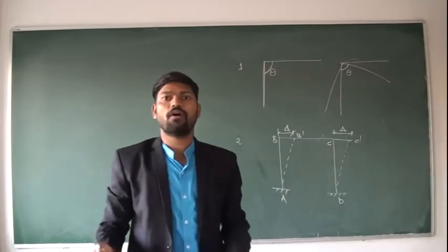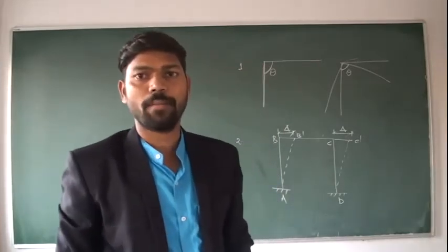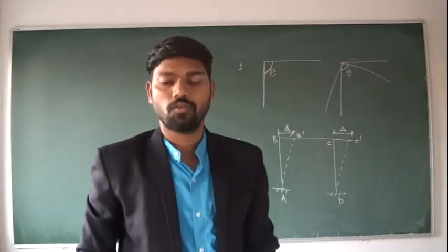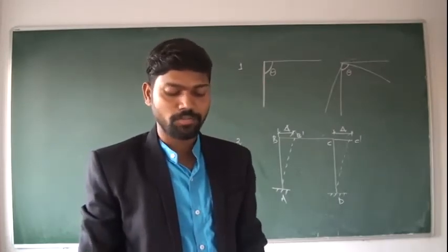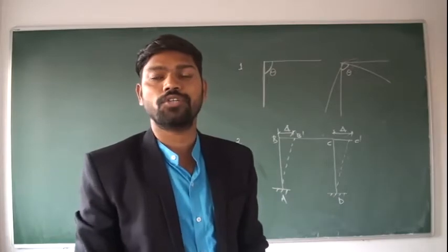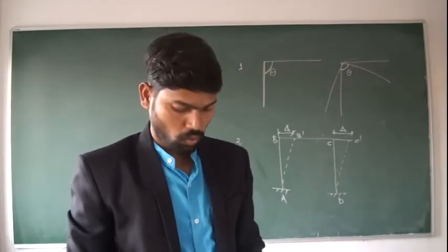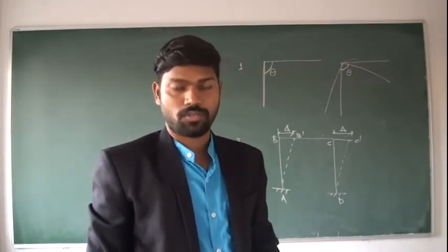Though the members are deformed, the angle remains the same. So this is our assumption number 1. All the joints are rigid and the angle between any two members in a joint does not change even after action of loading.